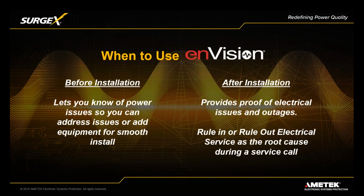Your power is so unstable, and you're in an office building, and you have no control over changing it, or maybe you're in a residential area and you've got no ability to improve the power. So now, I'm sorry, but we're going to have to increase the bill of materials to include an online double conversion UPS to get rid of these power fluctuations. So I think it's a great tool for before. And then for me, after, it's an insurance policy.